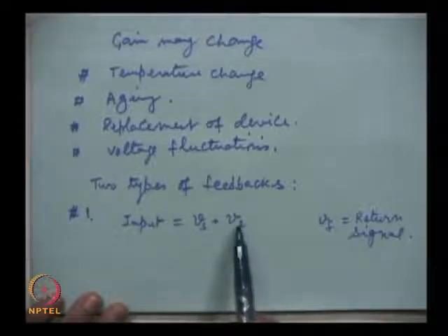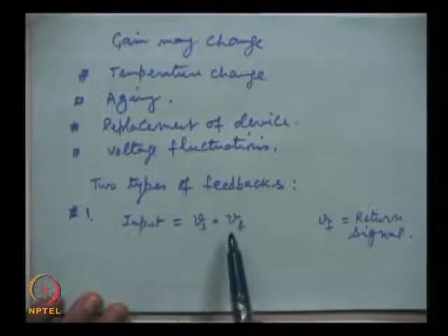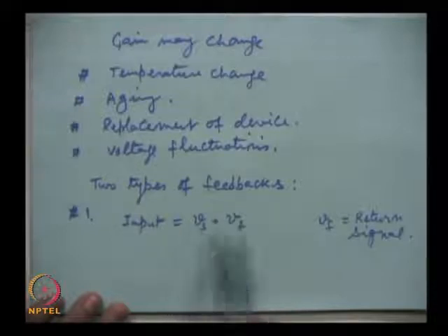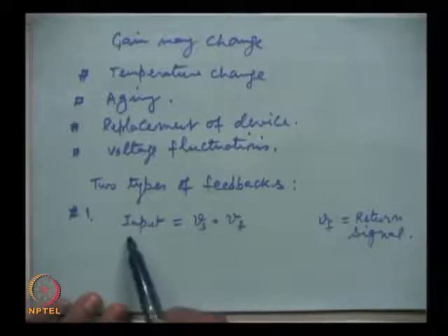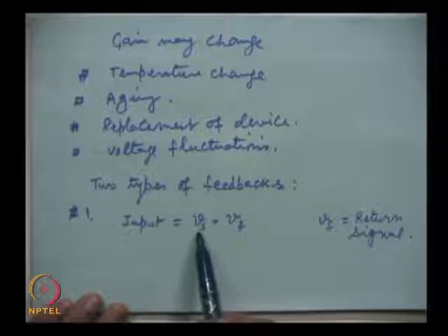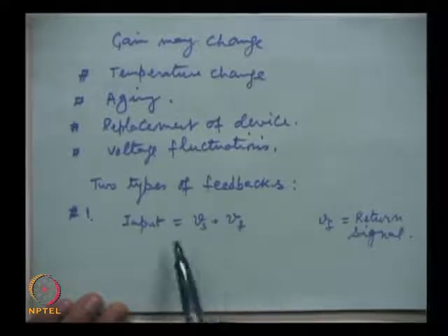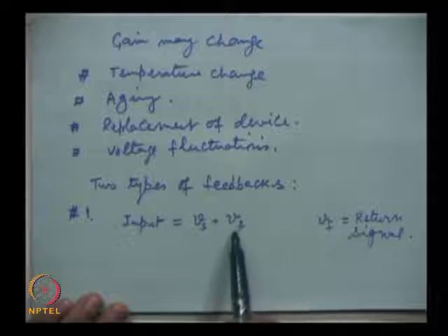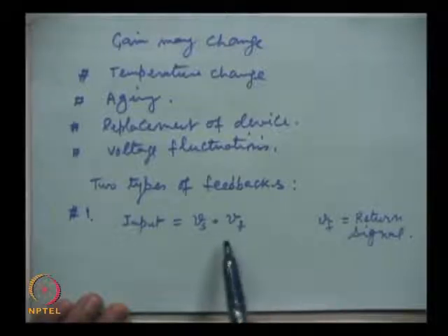So the phase of the return signal is additive, they are in the same phase, so that the effective input signal will be Vs plus Vf. This is the original input signal and this is the return signal, and the two are added up.